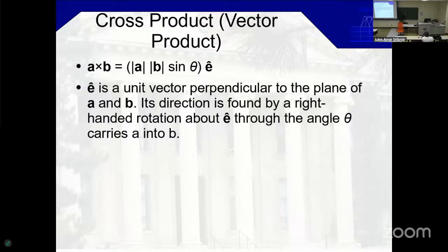So let's say that I have a few boreholes that I want made, or I have some structure to be placed. On my plan, I know the easting, call this P1, northing P1, easting P2, northing P2, and I may have a number of those, right? And I want to convert these eastings and northings into stations and offsets.